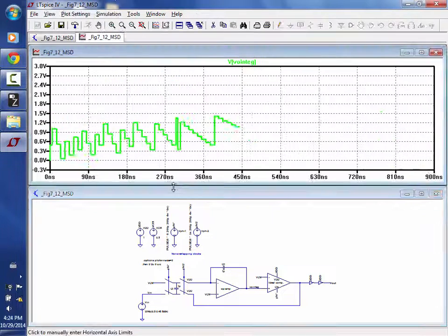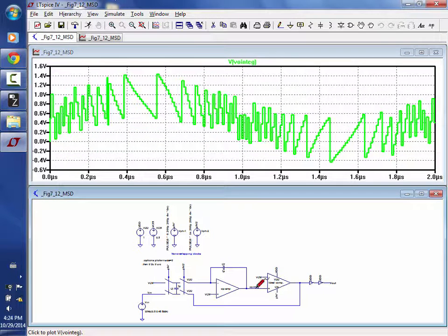We talked about this last time. And this is the output of the integrator, the output of the op-amp. So when you do your projects, you have real transistor circuits, you're operating with a 5-volt supply. If you start to see them saturate when you probe this node, you have to adjust the gain of your integrator. Okay, so if you look at this, you say, my power supply here is 1 volt and ground.